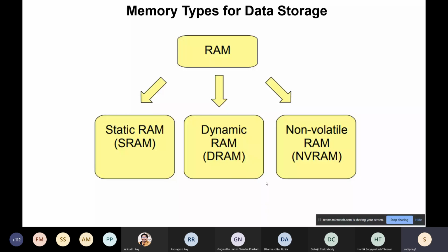Now, if you turn on the switch, that means the MOSFET, your capacitor will get charged up. If you turn off the switch, your capacitor will retain the charge. The point is that on-chip capacitors are so small and also leaky in nature. Leaky means the capacitors are not ideal. They lose the charge if you don't top up the charge. So if you don't recharge it after some time, your capacitor will automatically discharge because of its internal leaky nature and very small capacitance. Obviously, after some time gap, if you read the DRAM value, DRAM will forget everything.